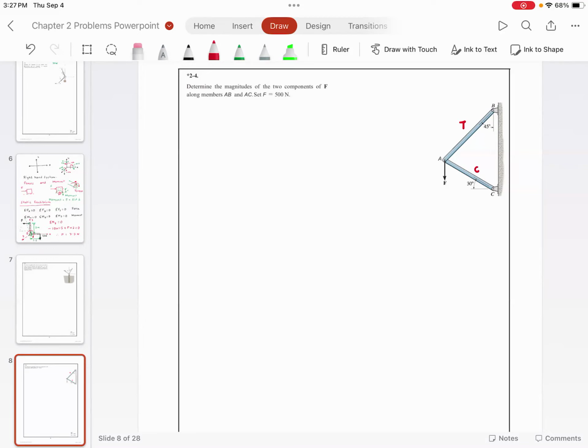Now, what I want to do is, and everyone please get it, it's a very important concept. I want to free each and every member. If you look at AB, AC, and BC, they are hinged together, so they are connected. So now I want to free these bodies, and I want to draw a diagram by freeing these bodies.